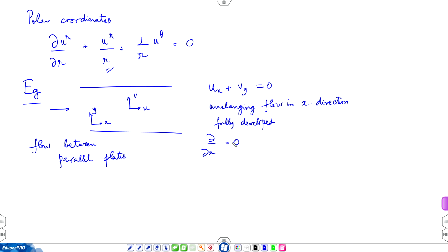Now, what do you expect the distribution of velocity to be? This distribution was not relevant in our global analysis, but now you are talking about local trends. So, what is the distribution? You may think we will solve for it later, but if you think about it, velocity has to be 0 at the walls, where the walls are fixed. If it is Newton's parallel plate experiment, then you would say velocity is 0 at one wall and equal to some given value at the other wall. If you have two plates, then velocity is 0 at both walls. So, just based on symmetry, you would expect the peak velocity to occur somewhere in the middle. Okay. So, you will have a bulging kind of parabolic distribution.